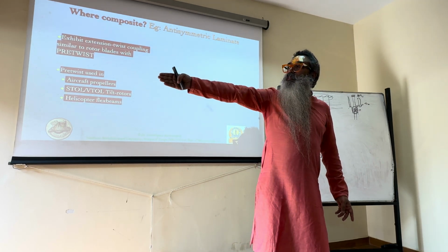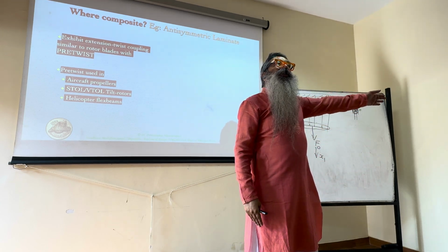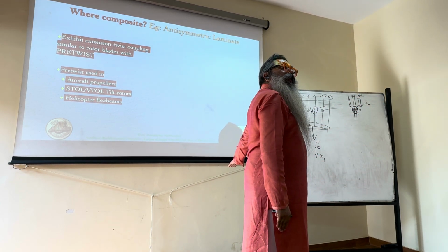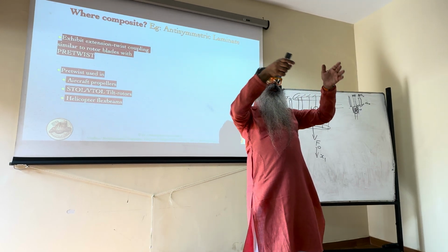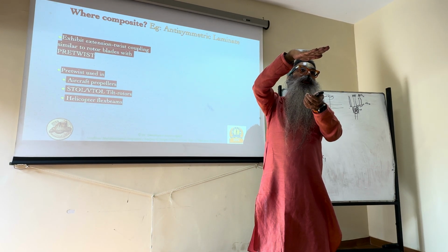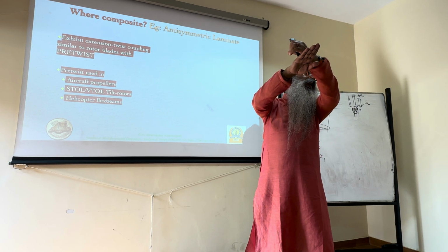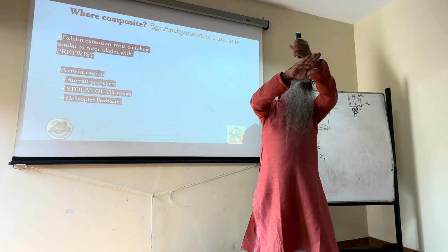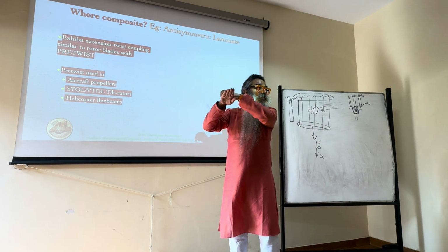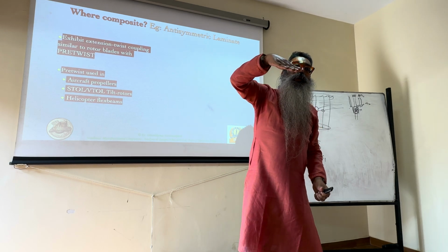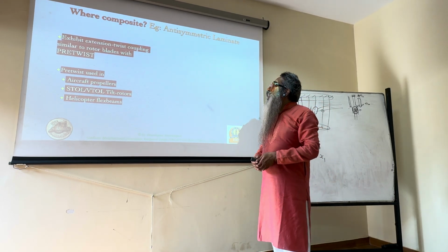So if I increase the pitch over here, the flap actually increases here, and if I decrease the pitch over here, the flap actually decreases here, so that the tip plane of the helicopter rotor blade, instead of being horizontal, now feels like this, and therefore the net thrust is always perpendicular to that. And so there is a component which is balancing the weight. There is also now a component which is trying to take the helicopter backwards, right? So similarly, you tilt it forward, to the left or right, to make the helicopter move in all those directions.